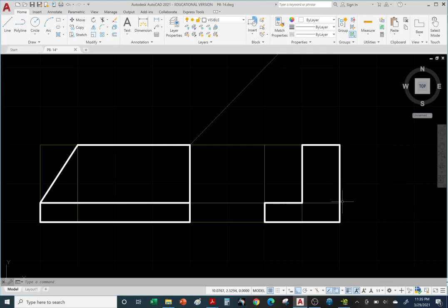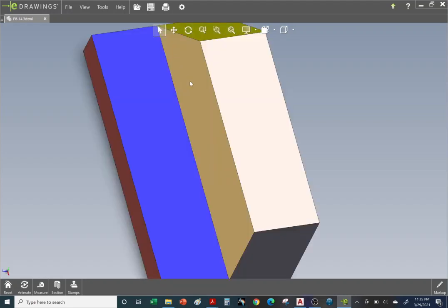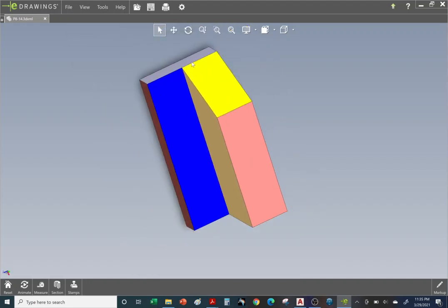Now we need the red hidden line, right? So now we don't draw a red hidden line here because we have the solid visible object line in front that's overlapping and overwriting it. So for this case here, we don't have an object line, so we do need to draw that red hidden line to represent the one on the opposite side. Okay, so red hidden line for this edge here, end of this chamfer.